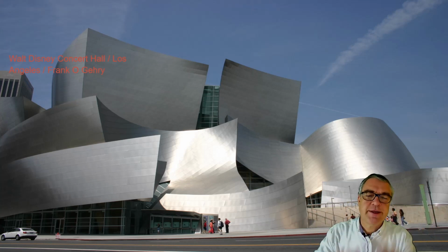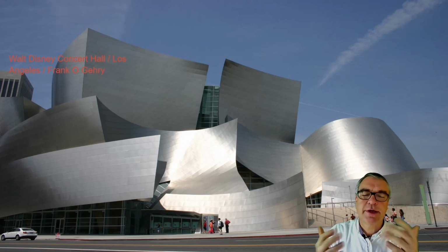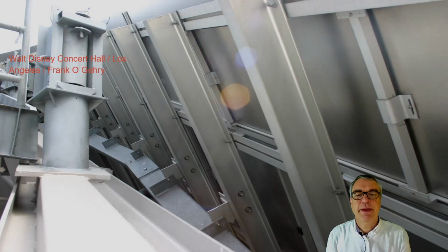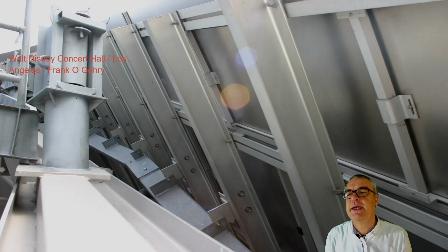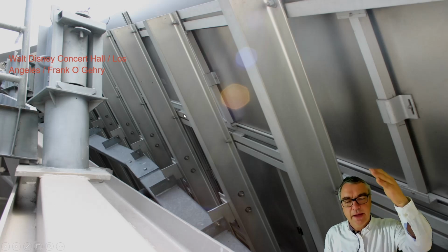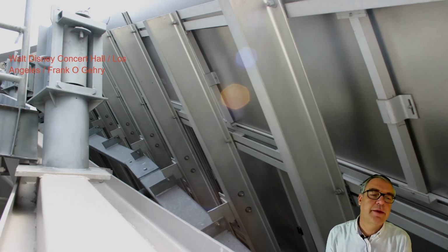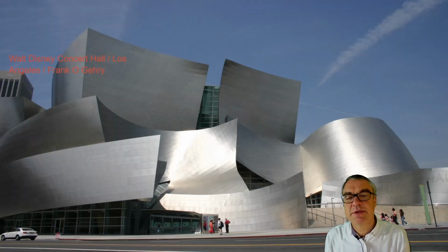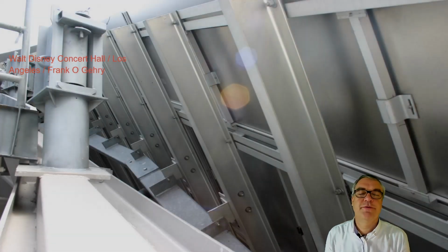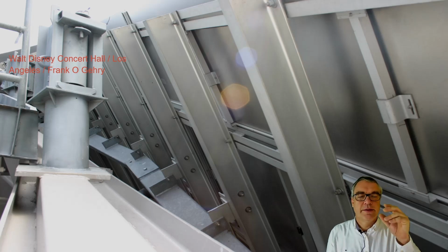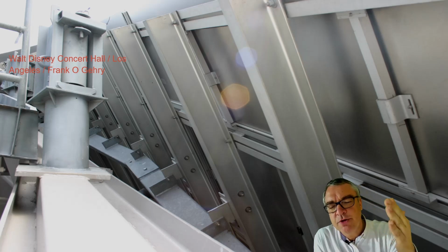We envision that there needs to be a shell-like structure behind, but technically speaking, it's a skeleton structure, which we see here: a main skeleton structure, which has a first secondary structure, second secondary structure, third secondary structure, which then allows positioning the shingle system on a final secondary structure. That's the shingle system which we see here on top of this structure. So it's a technical solution for creating this geometry, but when we think about it, it looks like a shell.